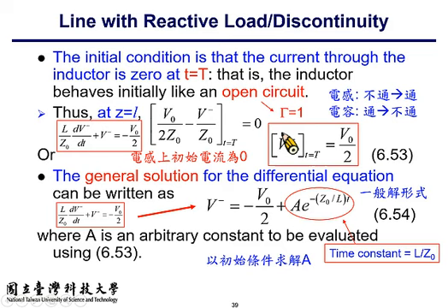So the reflection coefficient here is 1, which means the reflected signal V minus shall be the same as the incident signal V plus. That is V sub 0 over 2. Alright, so here is our initial condition. And based on the V minus description, you can write up the I minus current as well.